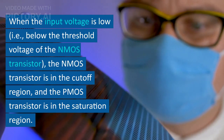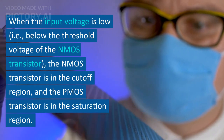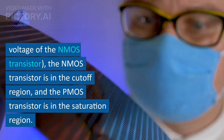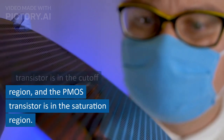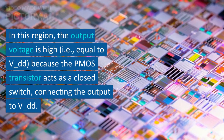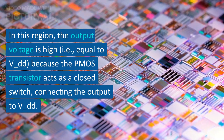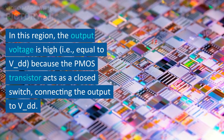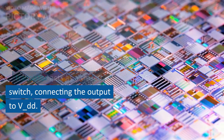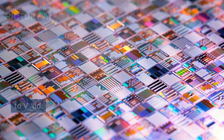When the input voltage is low, i.e., below the threshold voltage of the NMOS transistor, the NMOS transistor is in the cutoff region, and the PMOS transistor is in the saturation region. In this region, the output voltage is high, i.e., equal to V_DD, because the PMOS transistor acts as a closed switch, connecting the output to V_DD.